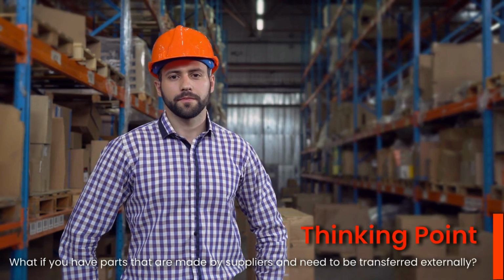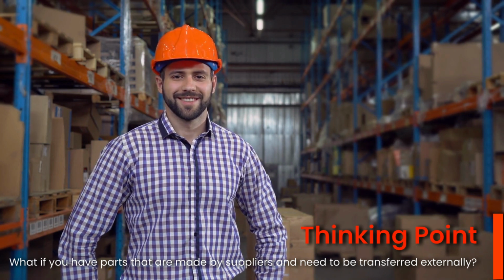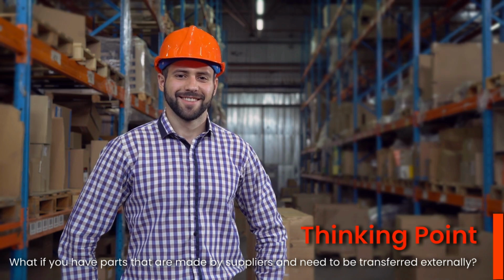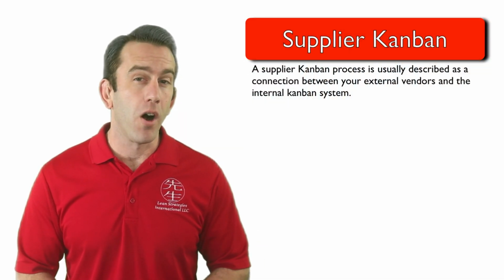When a Kanban system is running internally, the transfer of classical Kanbans into different areas can be established fairly easily. But what if you have parts that are made by suppliers and need to be transferred externally? In this case, a supplier Kanban is used in place of a withdrawal or a move Kanban.